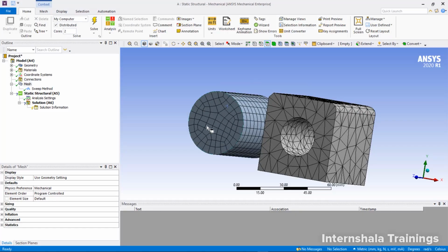You can take refinements, and if you want a good structure, you can split these objects. As I already told you, generating hexahedral mesh requires a lot of manual operations and a lot of theoretical background, because with simple settings we can't generate hexahedral mesh. Tetrahedral mesh can be generated somewhat, very good mesh can be generated with tetrahedrons. That's not a problem, even though we are using automatic meshing.